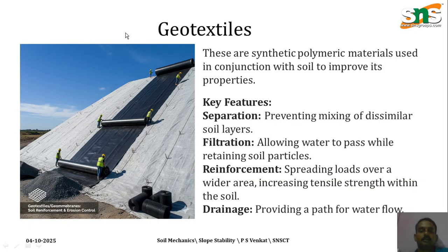Next, the final method is geotextiles. Geotextiles are synthetic polymeric materials which are used as layers to improve the soil properties. The various benefits are that it provides separation for different layers of soil. It provides filtration by allowing the water to pass, and also acts as tensile reinforcement which increases tensile stability of the soil, and also provides drainage for water to flow.